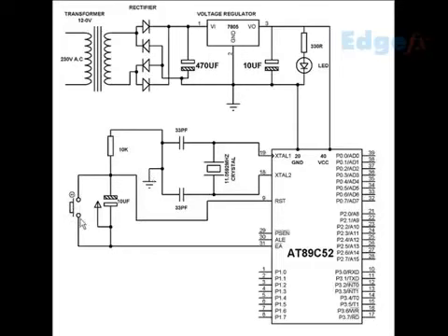And we have a switch, we call it a reset switch. The function is that when the supply is switched on, whether through battery or through supply, this capacitor from the positive supply starts conducting, or charging, so this point goes high.